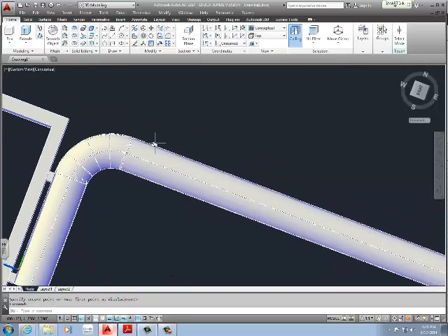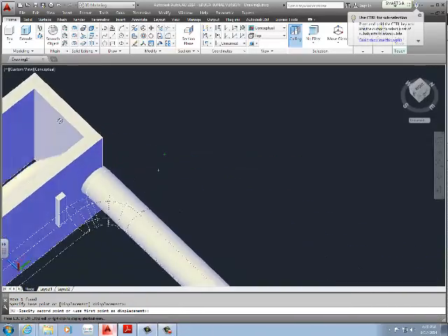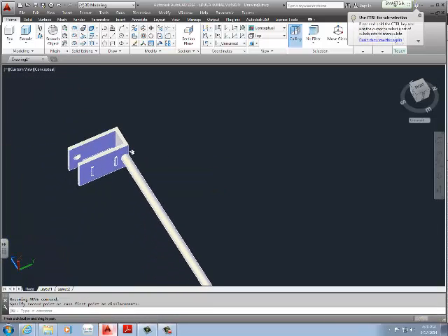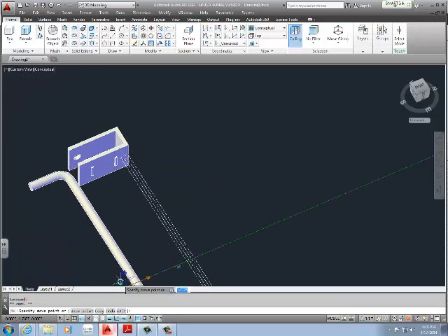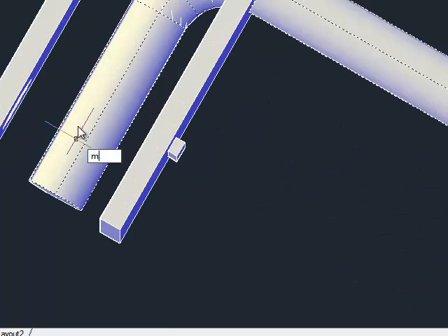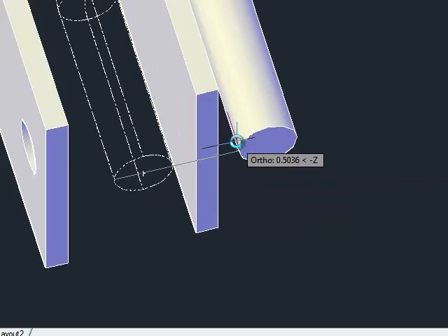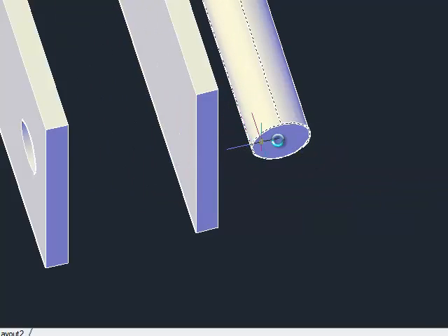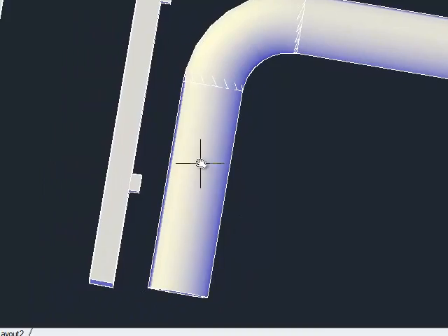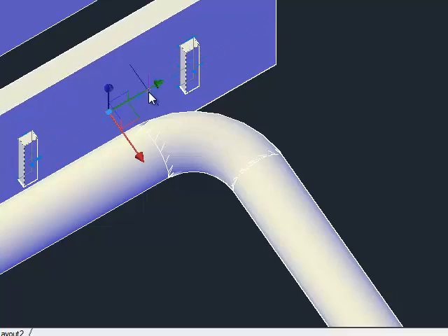So I'm going to move this object based on quadrant here to the midpoint of my rectangle. From there, moving it down the required distance of 0.32. And then I have to move it over. And I can use this as a reference. No, it's not going to let me get the quadrant. So as you can see, these projections are in the wrong position, so I can move them down again.